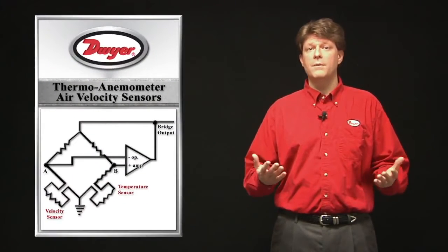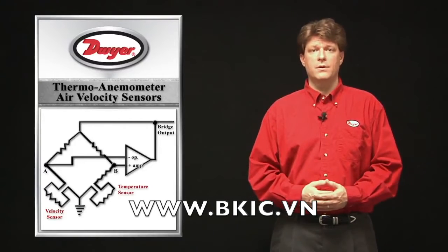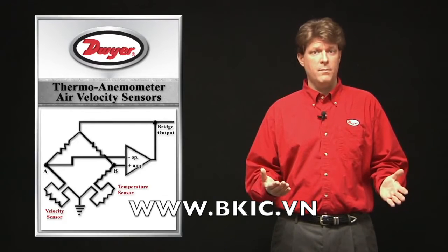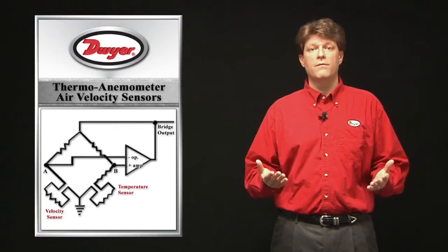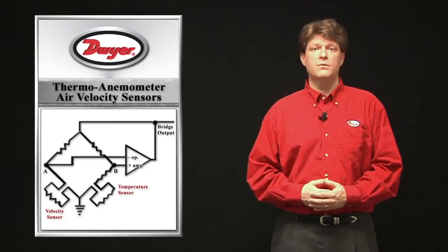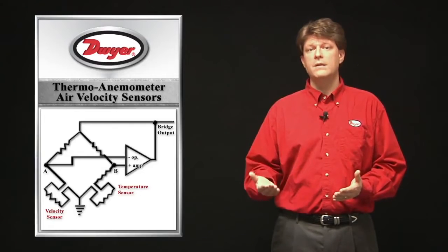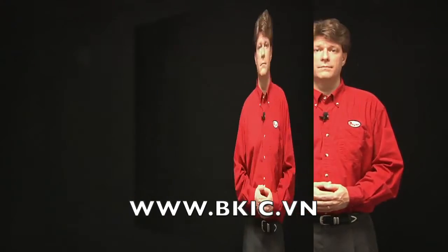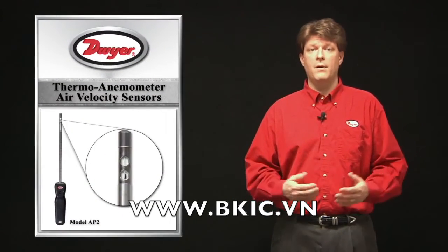Hot wire anemometers come in three basic types: constant current, constant voltage, and constant temperature. All three types have circuits that are based on trying to maintain a specific variable during the cooling effect based on Ohm's law. Thermo anemometers offer good low flow detection, fast response times, and high rangeability of measurements. They are omnidirectional, making them good for turbulent flows, and are easier to use than pitot tubes, but are more fragile than pitot tubes. Usually a probe-style sensor is made for insertion into ducts and pipes.